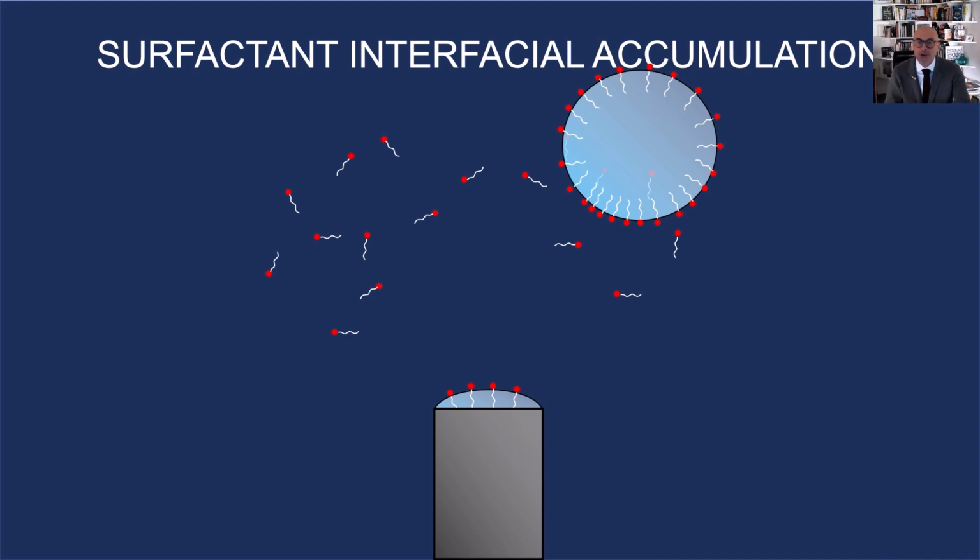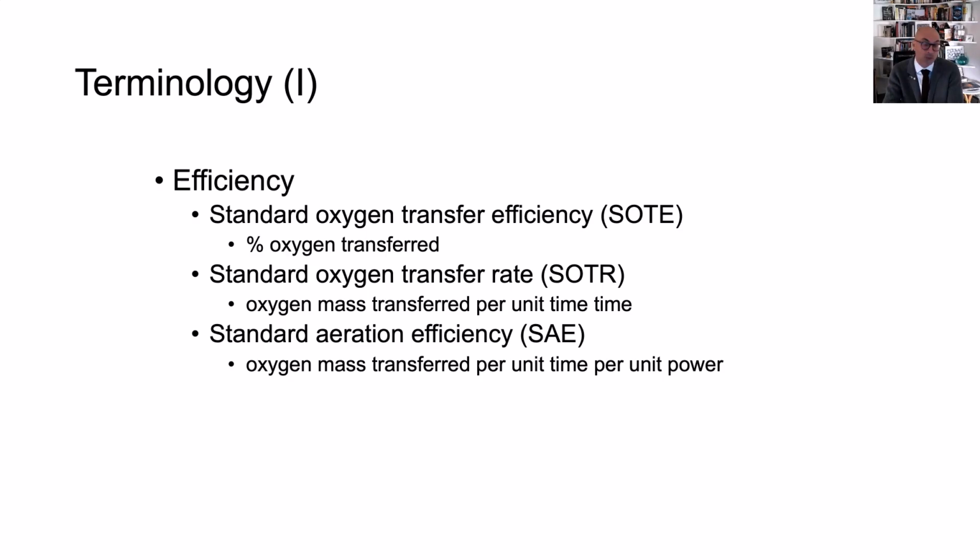Normally a bubble will have the gas inside circulating all the way to the surface, keep rejuvenating that driving force that drives oxygen transfer. With the surfactants, there is a stagnation film caused by those tails, and now the rejuvenation is much hindered. That causes the alpha factor to be below 1.